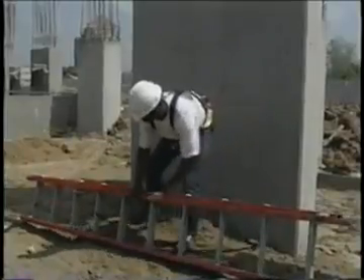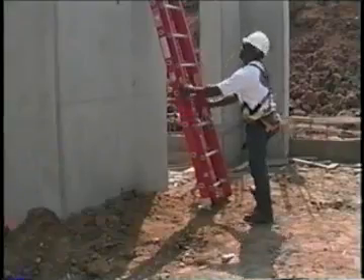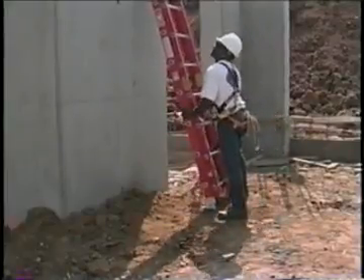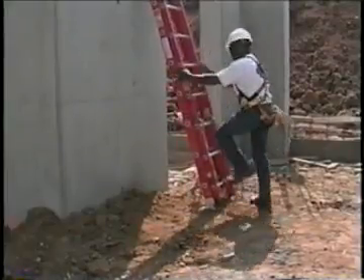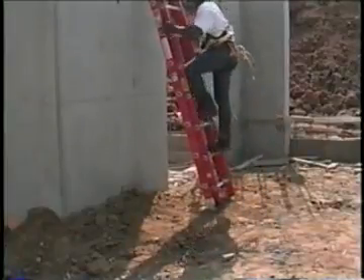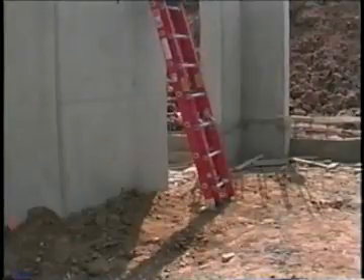Check the design strength of the ladder to be sure it will hold the amount of weight you'll be putting on it. To avoid having a straight ladder slip out from underneath you or fall backwards, position the ladder so that the base of the ladder is at the most stable angle for climbing. The distance from the base to the wall should be about 1/4 the working length of the ladder.